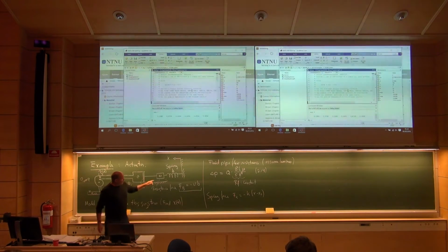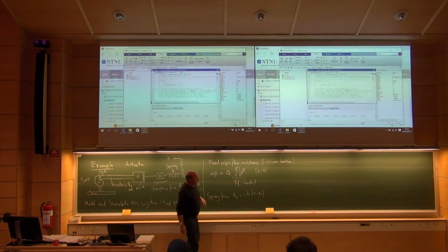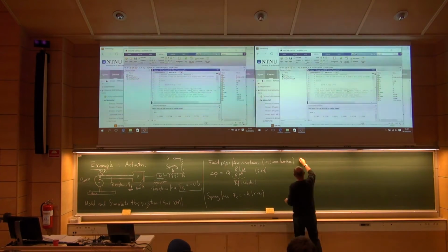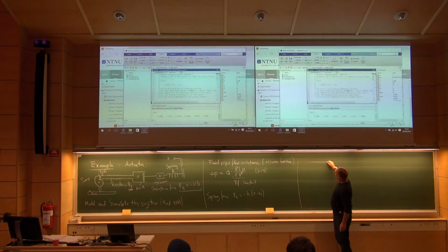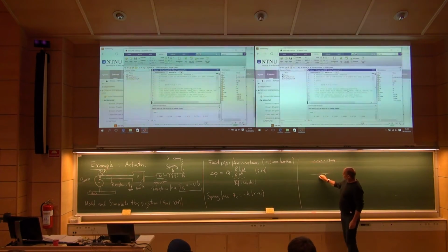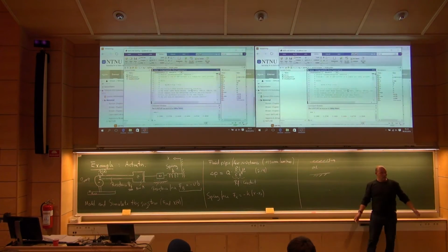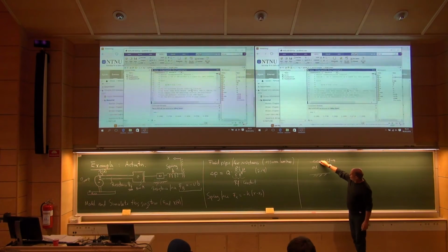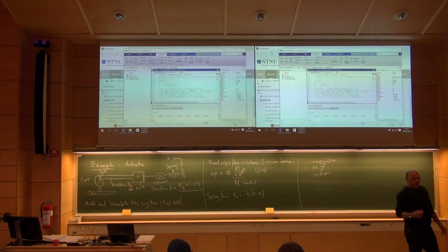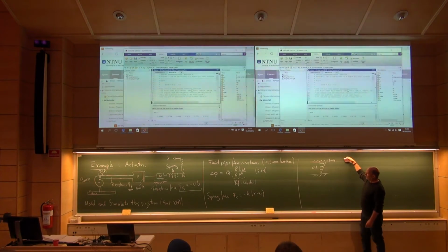Well, as I said, imagine a small oil film here. You should remember from basic fluid mechanics: a moving wall, a solid wall standing still, and oil in the center. What's the velocity profile? It's going to look something like this. Then you're talking about Couette flow. What's the force you need to use to drag this plate here?